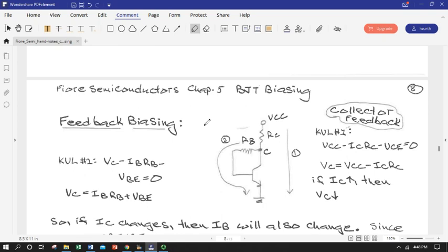This is very important because not only do we get some circuit stability in the fact that our beta relationship to our collector current is going to involve beta being down in the denominator of a fraction, kind of a double fraction, and being inconsequential if we choose the right value for base resistor versus emitter or collector.